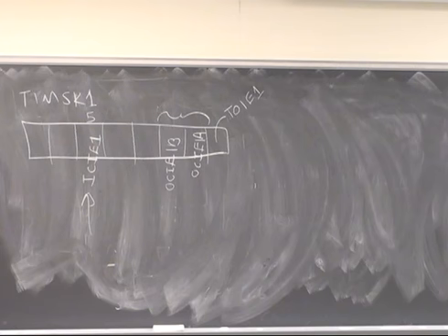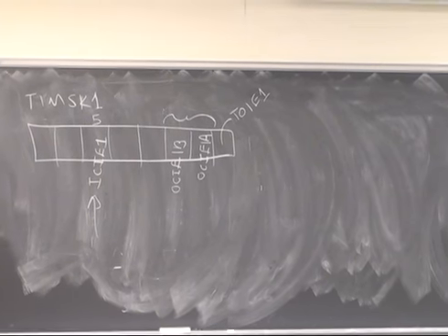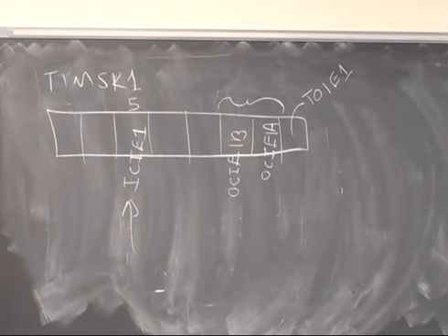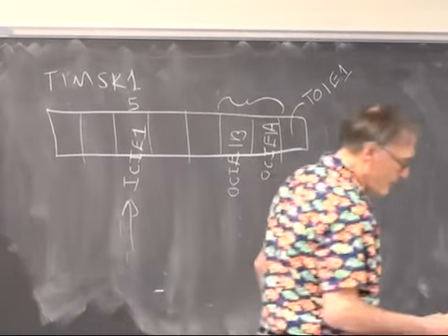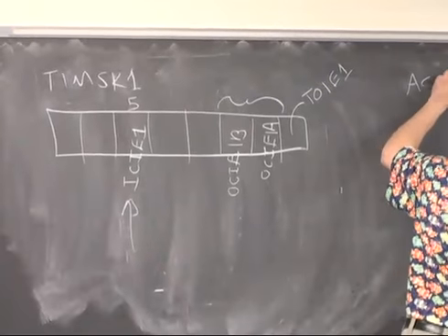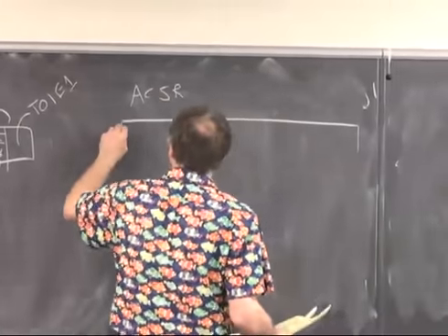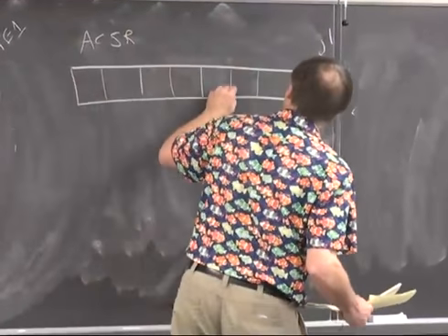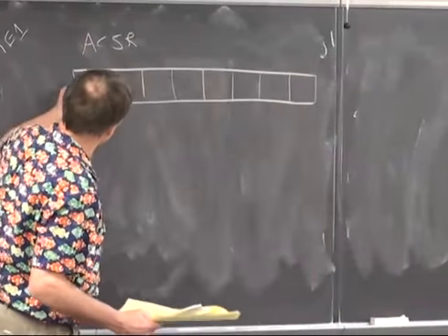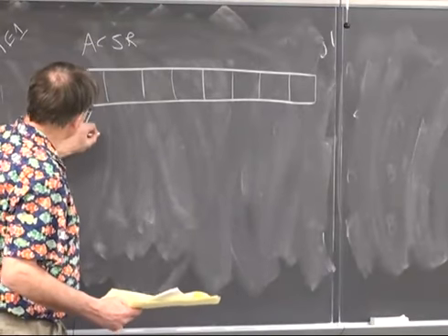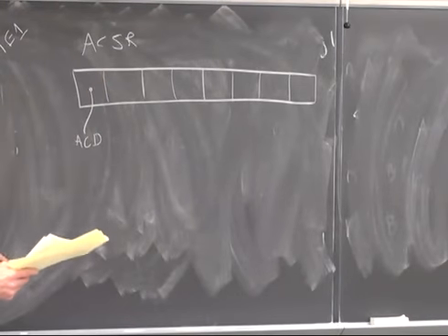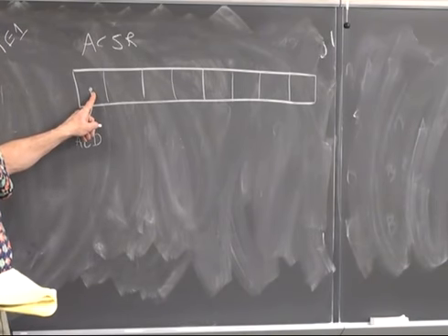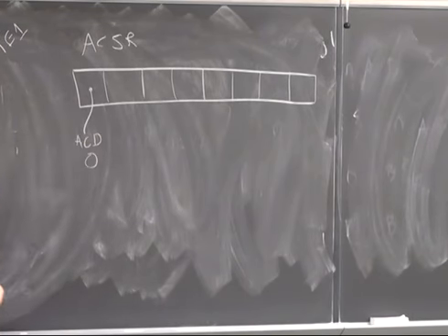Conspicuously missing from all of this is any mention of the comparator. Well, it turns out that the comparator bits are in a completely different location called the ACSR. In the ACSR, there's a control bit to turn off the analog comparator. And this is weird. Setting a 1 here turns it off. So leave this at 0 if you want to use the comparator.